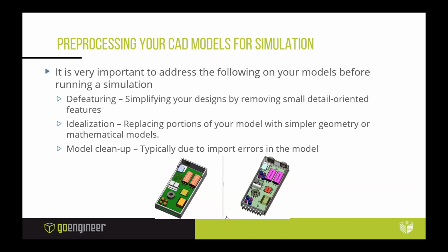All right, one more thing here is model cleanup. Who here imports from another modeling kernel into SolidWorks? Anyone imports geometry? A few of you? Okay. So this is going to be important for some of you, cleaning up your CAD data. Sometimes double check that if you are importing solid geometry, it's imported successfully as a solid, not a surface body. Double check things. We have in SolidWorks the import diagnostics utility that does a decent job at automatically fixing things. It's the closest thing to a do my job button we have in SolidWorks, right? So we have that capability that you can play with.